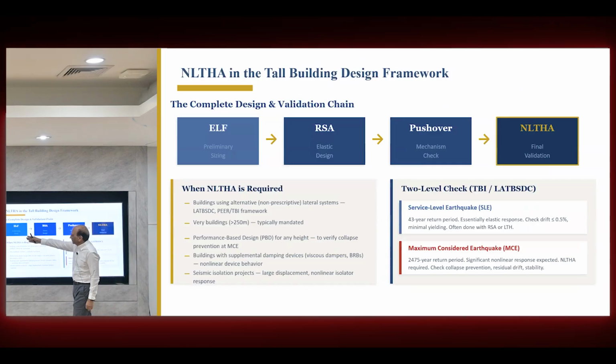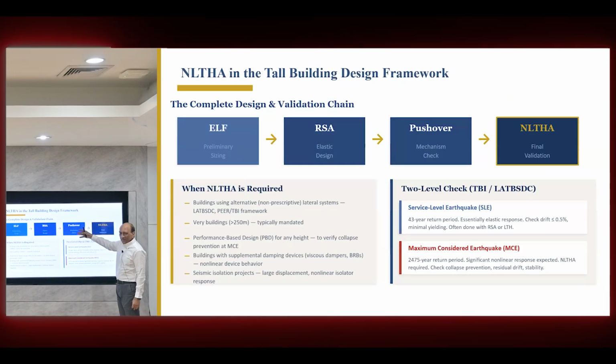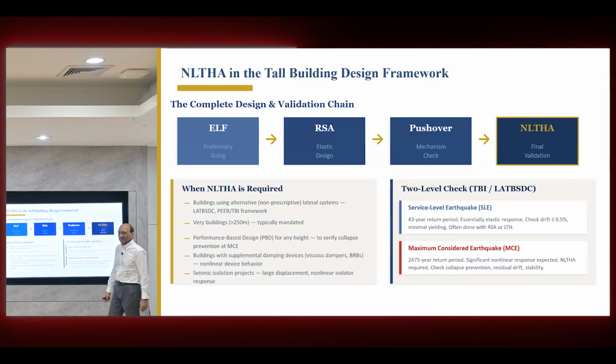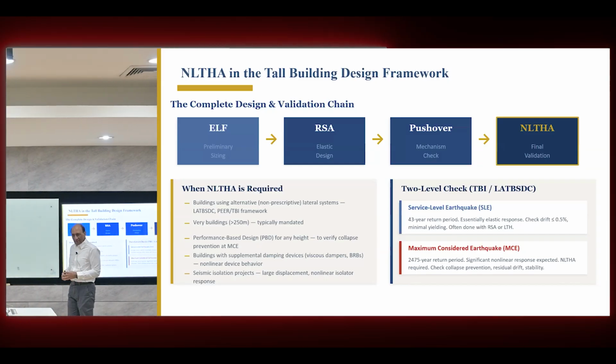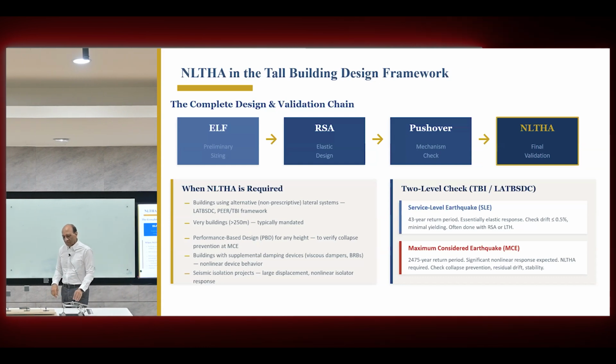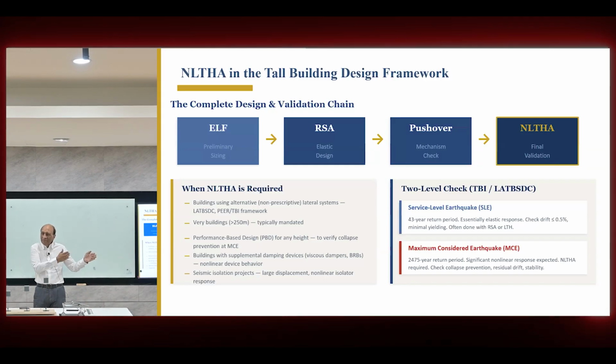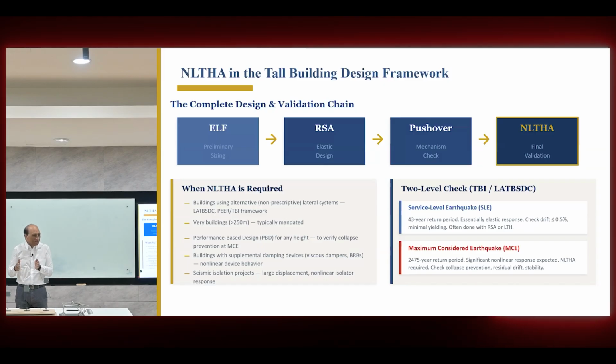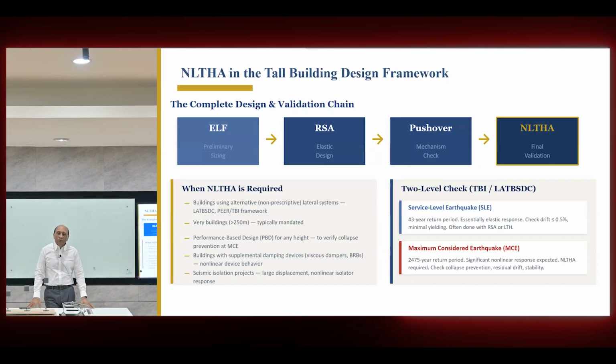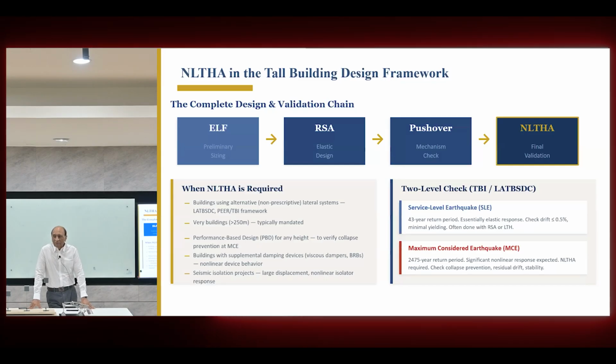So this is the starting preliminary design, response spectrum for initial design, then push over to check the mechanism, what is happening to the structure, and finally nonlinear time history analysis to check everything. So if you do the design seriously, you have to actually do all of them. You cannot ignore, as you go forward, you have to do everything behind also. And that's why when you normally come, you have a very good understanding of the structure.